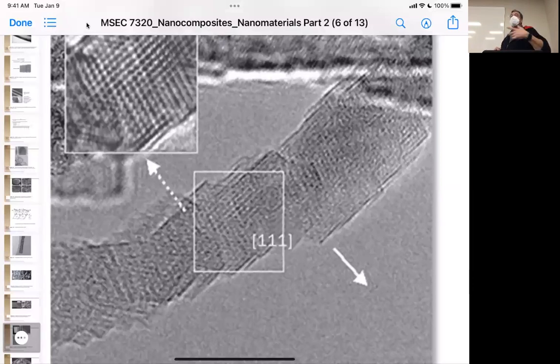So now we're going to look at something that we haven't talked about: density. Hollow tubes can be less dense than solid tubes. Hollow tubes can be just as strong as solid tubes because of the cylindrical structure. Solid tubes might have higher conductivity for thermal or electrical purposes. So again, application, cost to benefit ratio. That's what we're going to start talking about in chapter 3, and then each individual type. Okay.